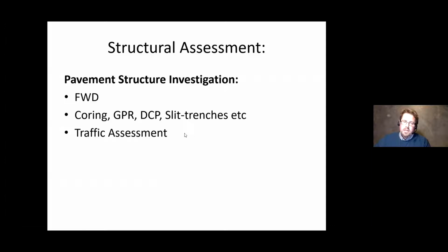And as critical as anything else is your traffic assessment. If you overestimate your traffic, you're going to over-design your pavement. If you underestimate your traffic, you're going to under-design your pavement. Getting it correct, or as close as possible, is critical. You're never going to get it exactly right, because there's too many unknowns. You could design a perfect road to last 40 years, and some eejit could go down it next week in a track digger. So it's a matter of just trying to get it as right as you can at the time.